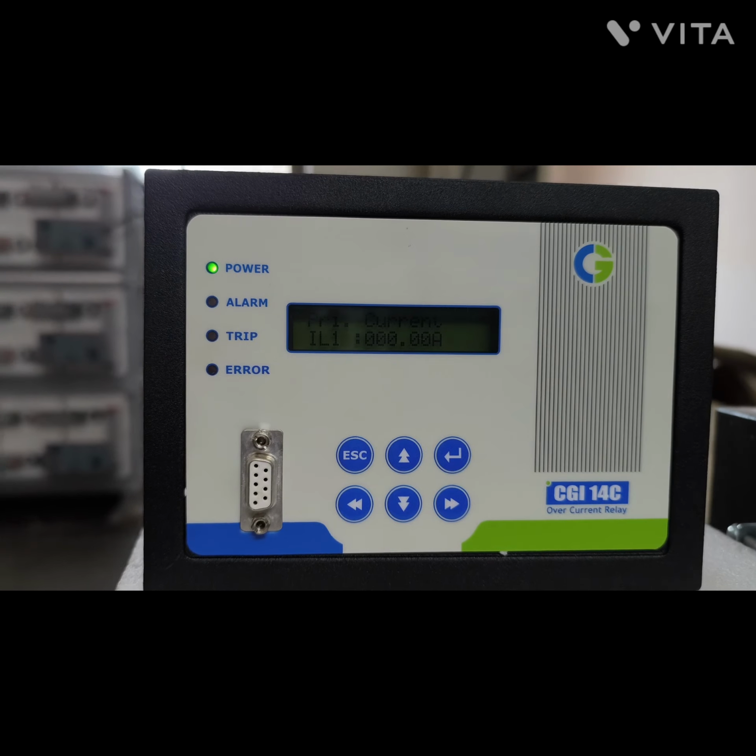Like that arc fault also has settings. Stage 1 is IDMT type, and stage 2 is instantaneous type. And one more is the test trip. To check whether the trip contact is activating through the relay or not, this is called trip test enable. If you press down here, you can see the trip test is enabled. So it is in the on condition. Just pressing escape, it will be reset.